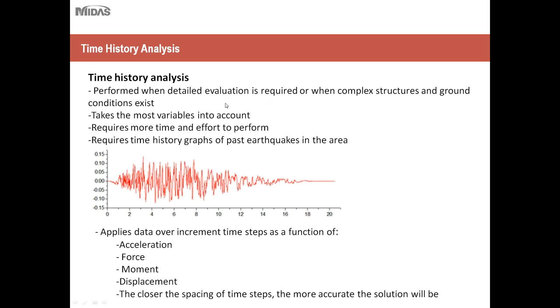The main concept to understand about time history analysis is that it's performed when a detailed evaluation is required or when complex structures and ground conditions exist. It takes more variables into account, requires more time and effort to perform, and requires the use of time history graphs or past earthquakes in the area. Time history analysis is really used for larger scale projects, and projects in high seismic regions where seismic design becomes more and more prevalent.